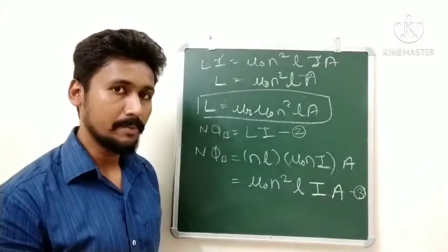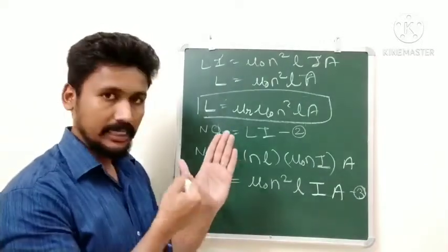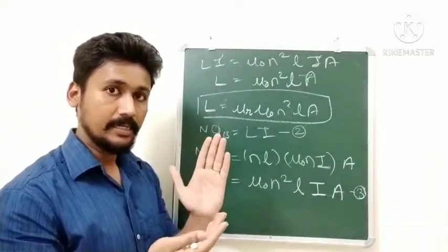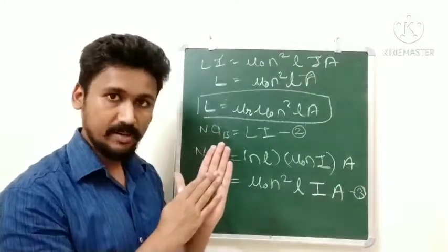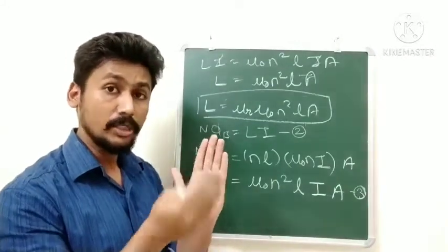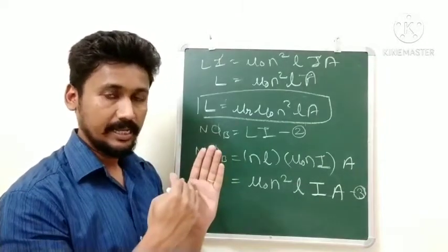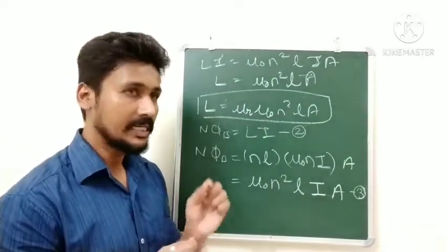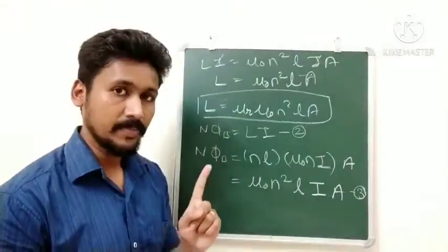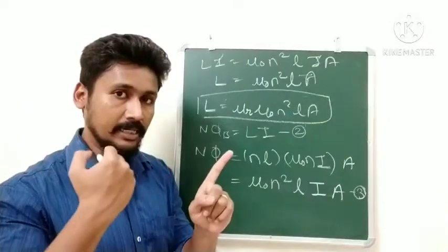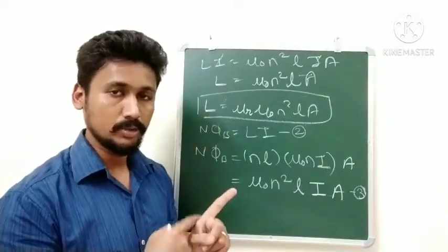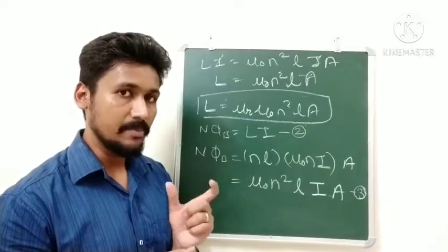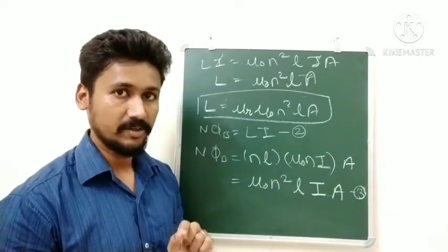Now another thing to remember about self-inductance. Current is going in the same coil, right? And then there is a magnetic field being developed around it, which is actually opposing the current that you had started with, right? It is producing something called a back EMF. So basically what happens is, if a coil has self-inductance, it is going to oppose the original current that is going through it. So that is why this EMF is given one name, that is called a back EMF. Okay, so I hope you understood the concept of self-inductance.